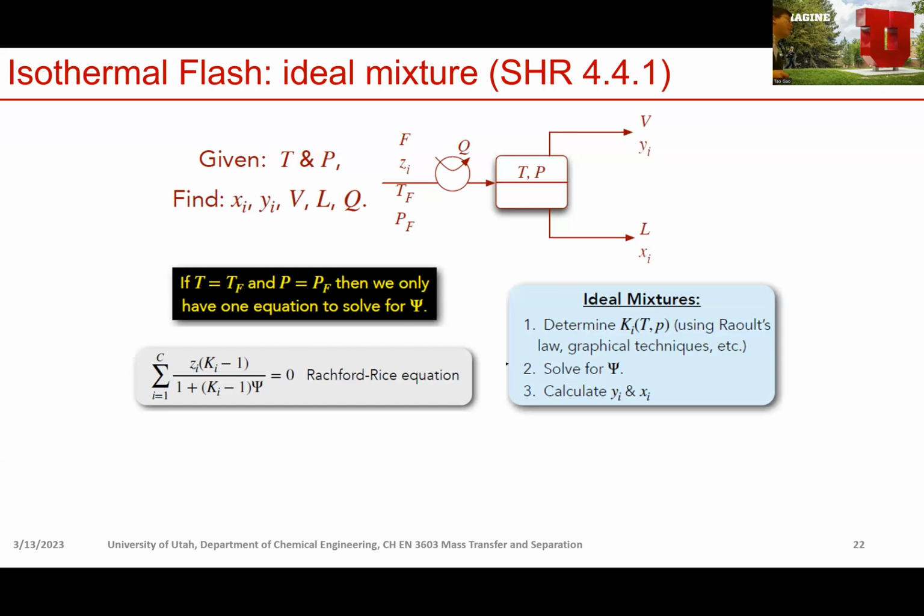You plug in the value of psi into this equation, the Rachford-Rice equation, right? Then you will get the value of this whole term. But that value is not necessarily zero, right? Because your initial guess might not be exactly the root of this equation.